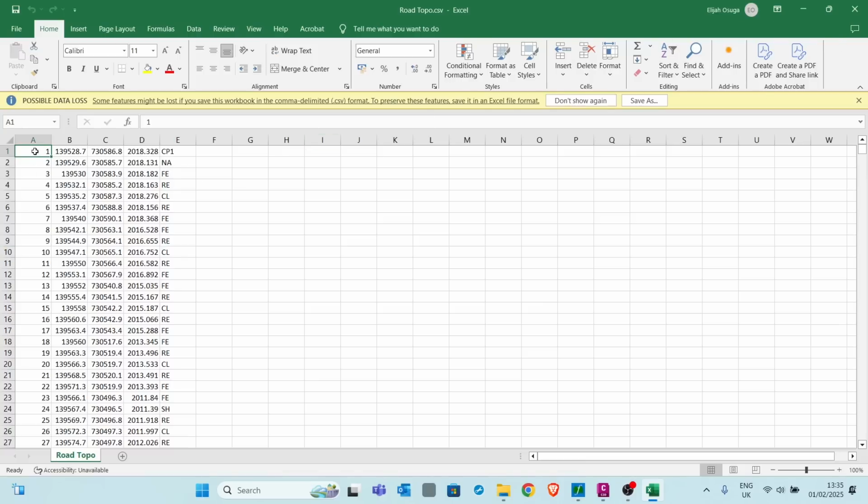So we need to have P for point, then E for eastings, and then this for northings, and then this for elevation, and then this for our description. So this is a PENZD file. That is our filtering format. Let me count this: 1, 2, 3, 4, 5, 6.